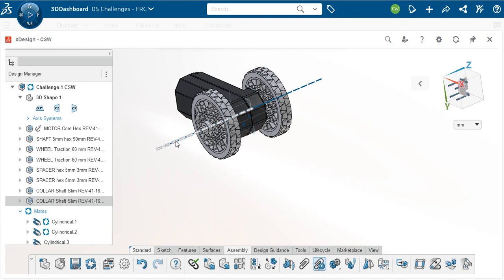And we could do some things to get rid of them if we wished. One thing we can do is click on that axis. I just left clicked on it and see the fly up we have. It says hide it. So let's hide that axis. Let's go through and hide this axis.